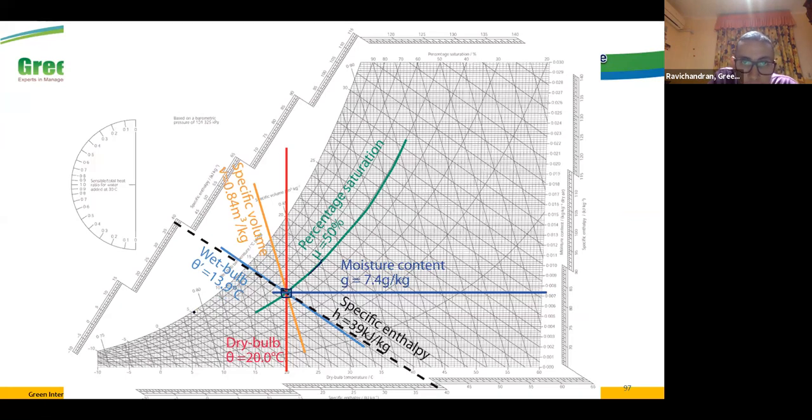Where is the line for 100% relative humidity? This line, relative humidity 100%, is the last one. I check this value here, which is 5. Take this 5 and go down. What will we see? I will see the same value 5 here. So the inclined line here, 5, refers to wet bulb, not enthalpy. Let's see 0. Let's go vertical like this, 0. So here the inclined line refers to wet bulb temperature.